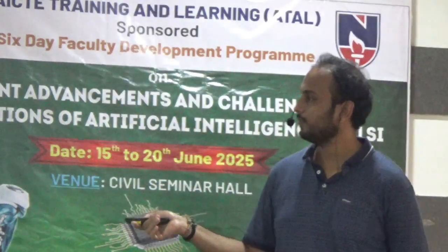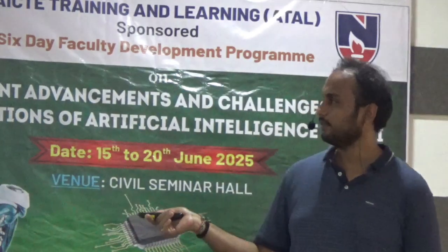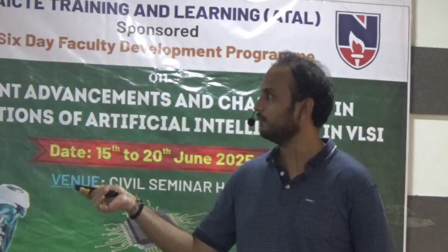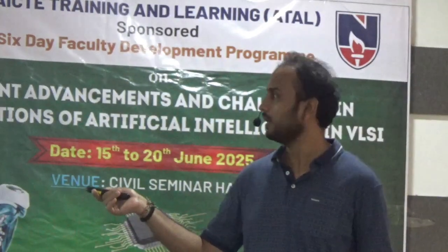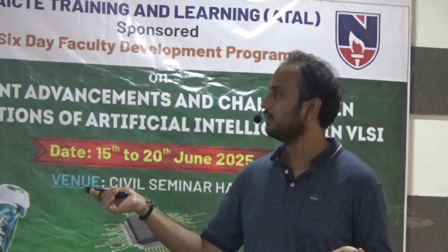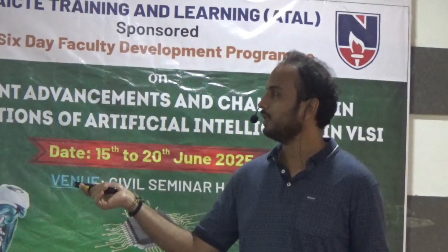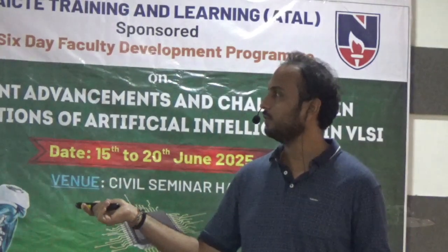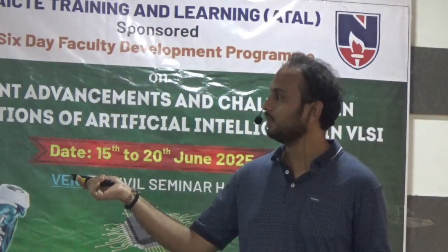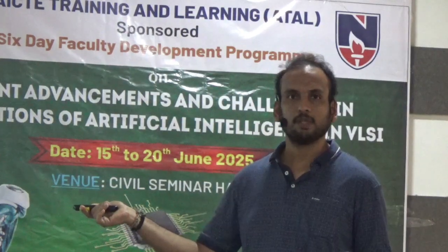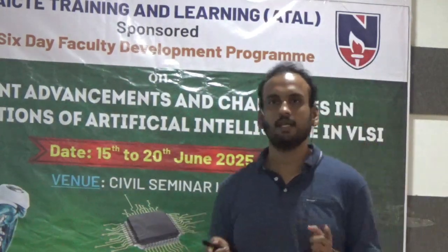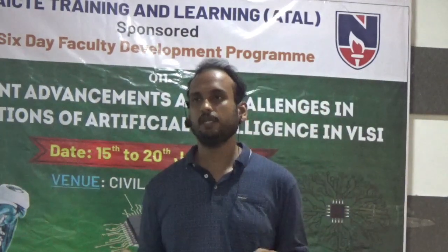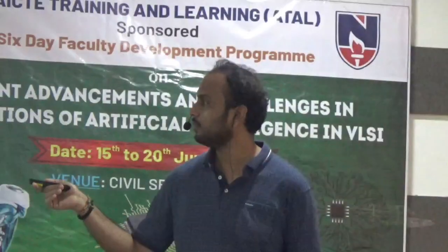If you observe the comparison between the 150 nanometer and 20 nanometer devices, you will get more output power. Yes, definitely you will get more output because your gm is more in that device. But what is the trade-off? The trade-off is you cannot operate at higher power. You will be somewhere around -10 dBm if you want to operate this 20 nanometer device, and if you go with the other device, you can operate at +10 dBm. This is the difference. Earlier I said that in lower technologies you will get more transconductance, but the range will be limited. This is how we demonstrated it. You get more transconductance.